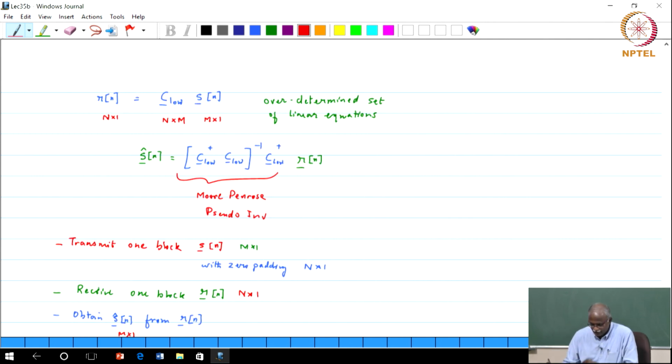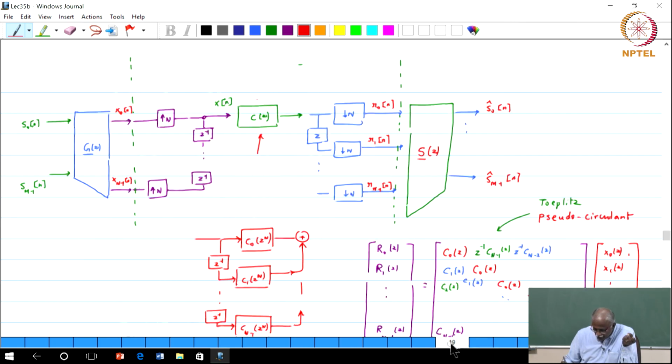Okay. So, here is a key observation. This is the structure of a block receiver. Now, one of the issues that we are going to have to deal with is, where are the zeros inserted? In x of n. That means there are certain points where you have said that the transmitted signal is 0, which means that there is nothing going on the channel. Point number 1 is, is that the right thing to do? Basically you are wasting time, but you are saying, well, that is the way I get to eliminate the interblock interference.